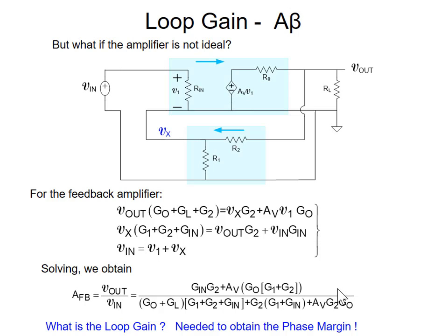If we take this amplifier structure and include modeling of the input impedance and the output impedance of the A amplifier, and include the load resistance, we can sum currents at 3 nodes in that circuit, and write these 3 equations. And it's not too hard to solve. And we find the gain with feedback is given by this expression here.